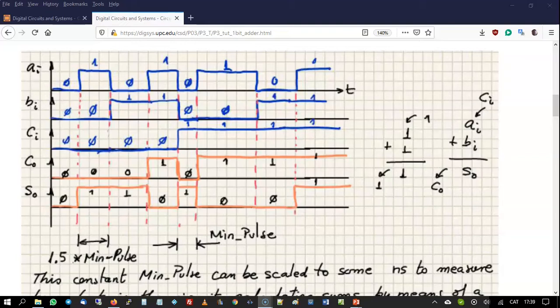If you've got 0 in the input A and 0 in the input B, but 1 in the carry input for a while, the inputs are going to be frozen to this value, 0, 0, 1. This is one of the combinations of the two tables, the one which gives you an output of 0 in the carry out and a 1 in the sum, right?